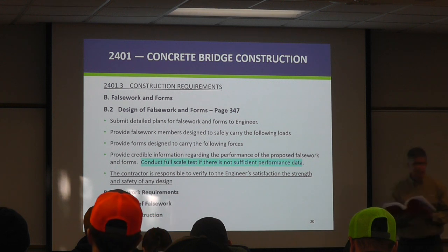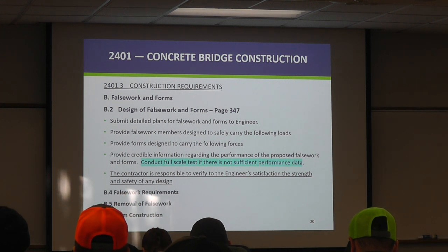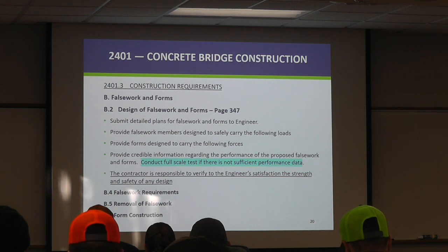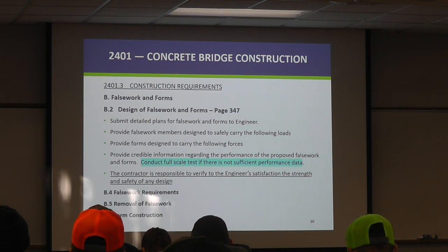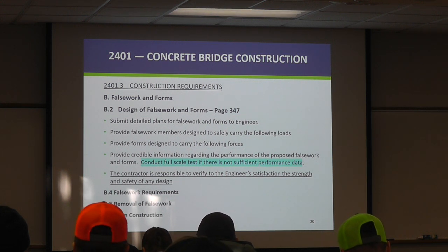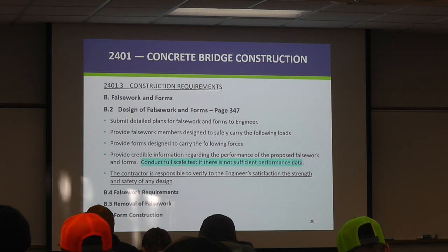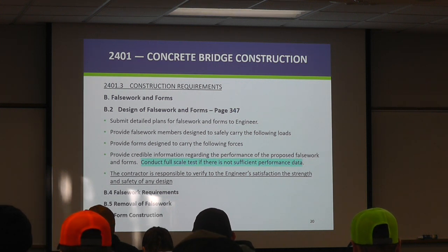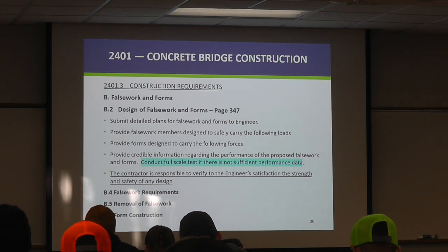And so, under this part of the spec, let's first talk about design of falsework and forms. On page 347, down at the bottom, B2: submit detailed plans for falsework and forms to the engineer.